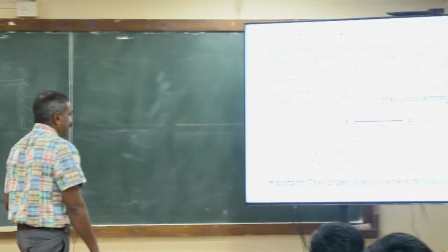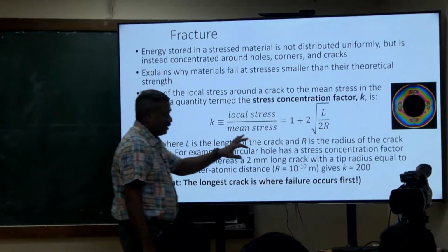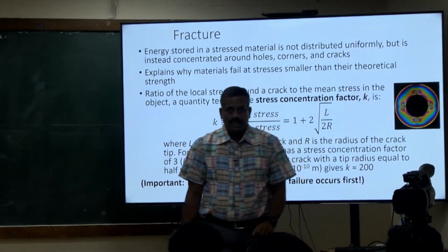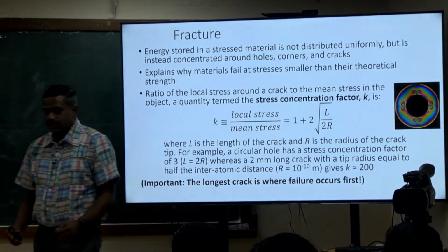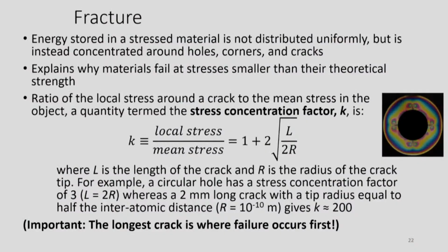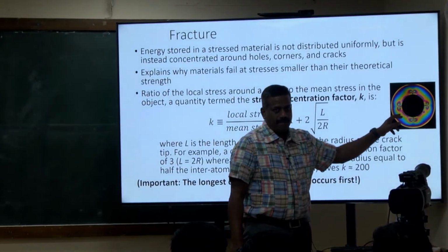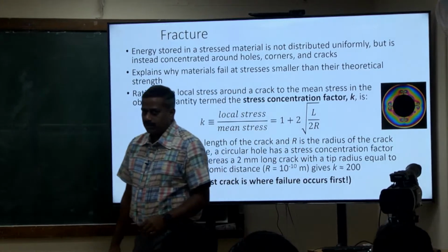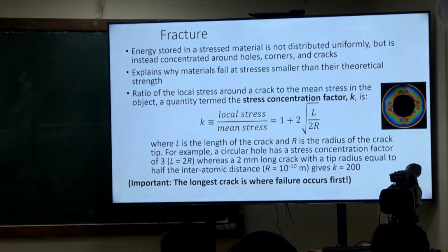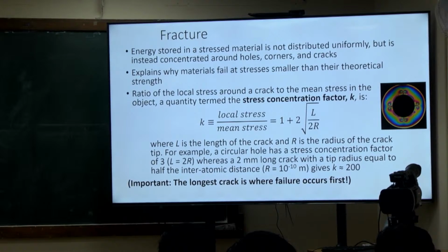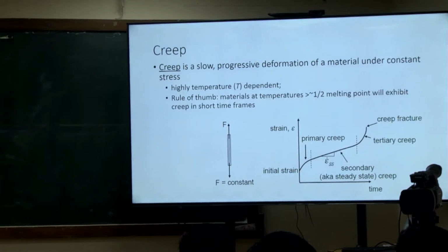Fracture energy, again, fracture will depend on the stress concentrations. So again, if you have a corner or some cracks on the surface of the materials, there will be higher stress concentration around those cracks and on the surfaces. Okay. So that will be the highest probability place where it starts breaking. Okay. So that's what we characterize using the fracture test. I'm just quickly going through.